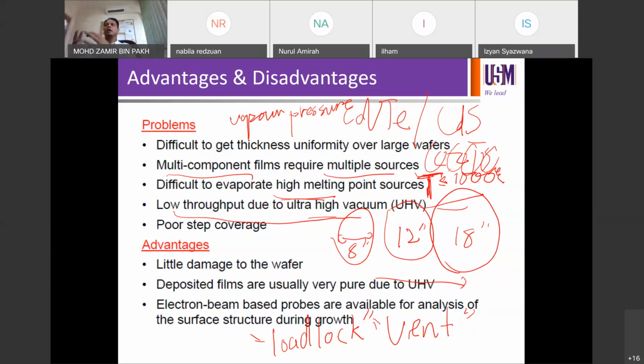So it's going to introduce potential contamination into the chamber every single time you open it, right? And this is not tolerable for mass production. For a lab it's okay. For mass production, this is a big no-no because you have to repeat unnecessary processes. So you might as well have a load lock and do it properly. So that's what it means by this point.